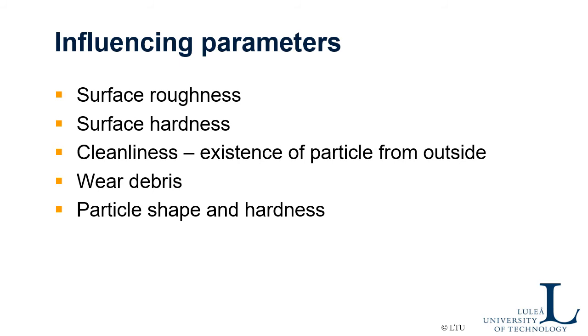So it's important to keep the system clean here, because if you can keep particles from outside away from the contact, then you reduce the risk for abrasive wear. And of course you should also avoid the wear itself, because that could accelerate it.